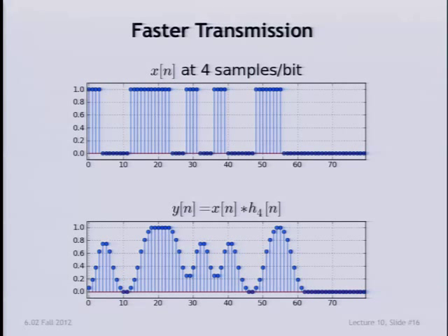But what's happening now is you've gotten so ambitious with how fast you want to get the bits across that you're not giving the step response time to settle. So over here, yes, there's time. The step response went up and settled because you had three 1s in a row over there. But now you're going down to 0 for one time instant and then jumping right back again. Well, here's the flipped over step response, and it doesn't have time to make it all the way down.